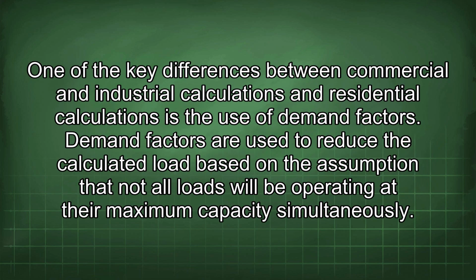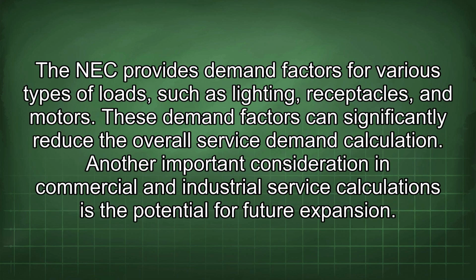One of the key differences between commercial and industrial calculations and residential calculations is the use of demand factors. Demand factors are used to reduce the calculated load based on the assumption that not all loads will be operating at their maximum capacity simultaneously. The NEC provides demand factors for various types of loads, such as lighting, receptacles, and motors. These demand factors can significantly reduce the overall service demand calculation.